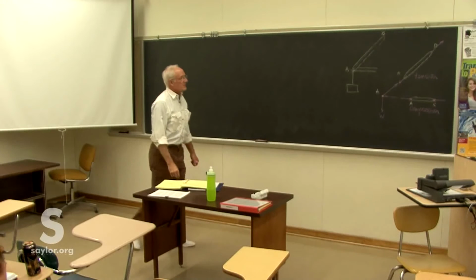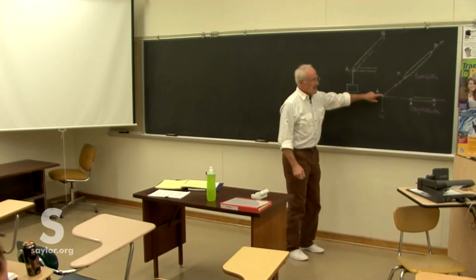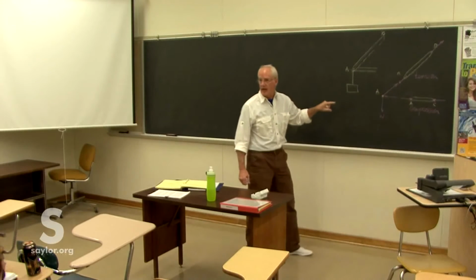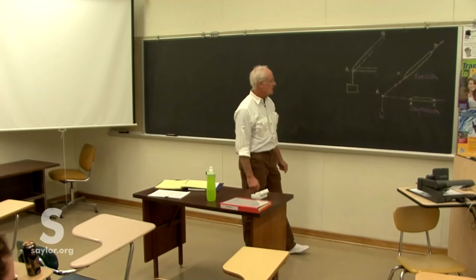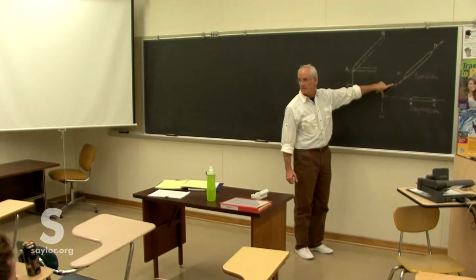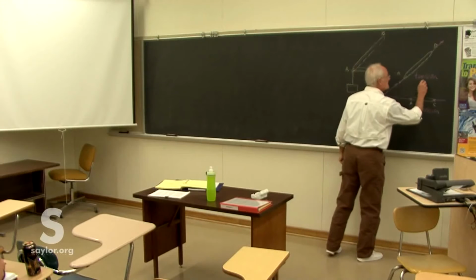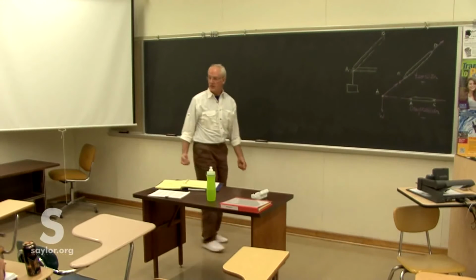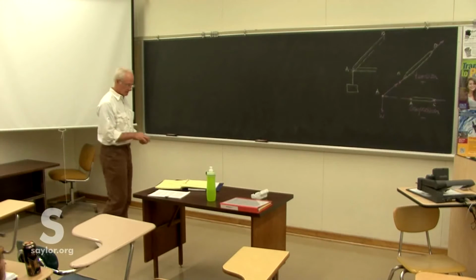So, in general, perhaps an easy thing to do is, anytime there's a force and you don't know the direction of it and you have to just take a guess, and we'll see some of those coming up in the sample problems, go ahead and guess that it's in tension. Then when you solve for it, if it's positive, you're right, it's in tension. If you're wrong, it's negative, then it's in compression. And we can use that as sort of a guideline.